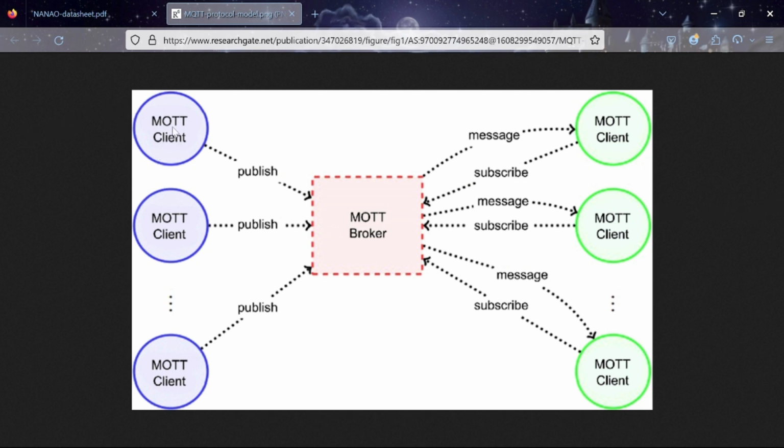So when I wave a hand over this blue Arduino, the message is published to our MQTT broker. Then the broker searches for another client who has the same topic. The topic is the thing that we would be inserting in our code, so we will discuss it later. When everything matches, the message is sent to our client, which is connected to an LED bulb. As I will show you later, we have to develop a code. So when we wave our hand in front of our main Arduino, which has the ultrasonic sensor, our LED bulb will be glowing.